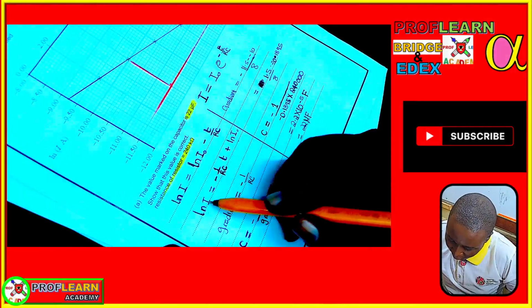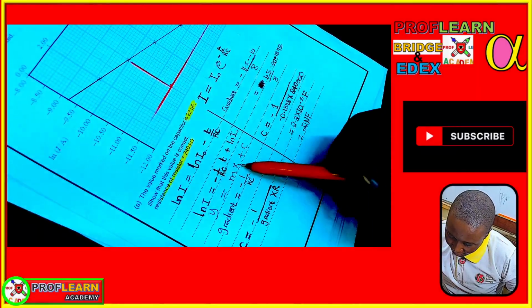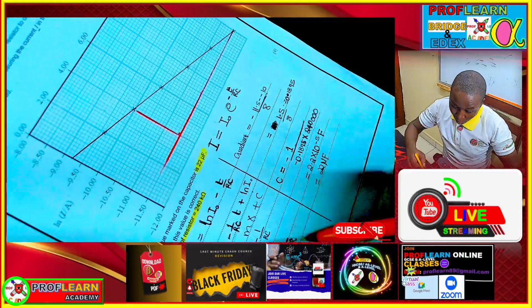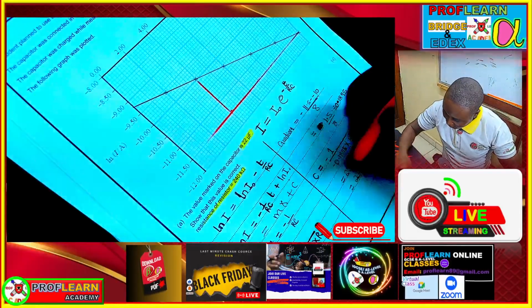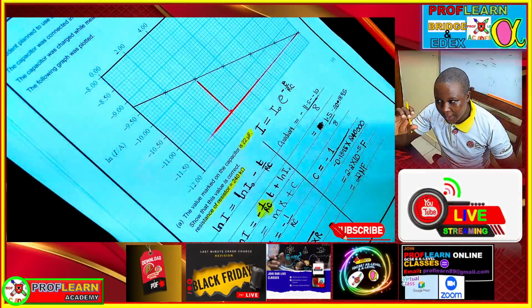If you rearrange this equation into the form y equals mx plus c, you realize that our x is the time, which is on the x-axis, and our y-axis is going to have ln of current. So ln of current is on the y-axis, which means that this section, negative 1 over RC, is going to represent the gradient of this graph.